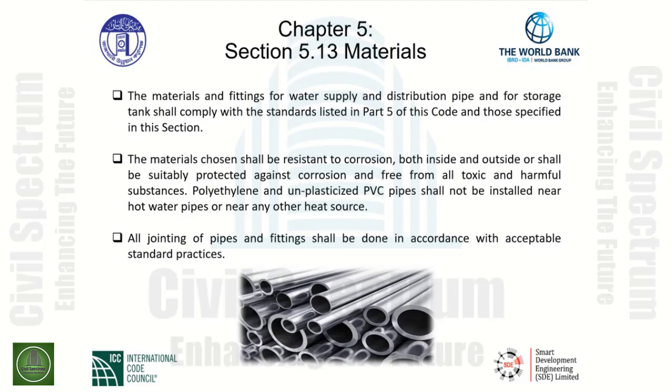The materials chosen shall be resistant to corrosion, both inside and outside, or shall be suitably protected against corrosion and free from all toxic and harmful substances. Polyethylene and unplasticized PVC pipe shall not be installed near hot water pipes or near any other heat source, due to the fact that these materials will combust, they will melt, they will deform near high heat sources.